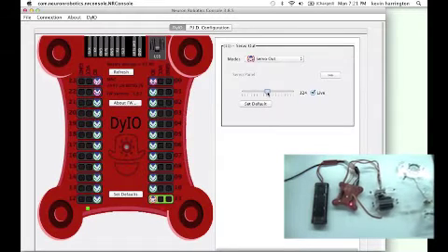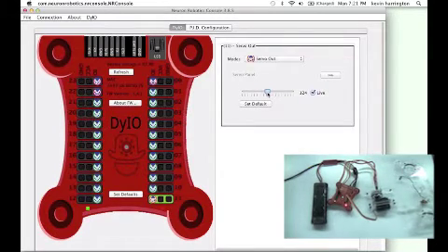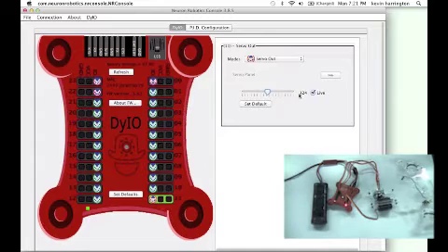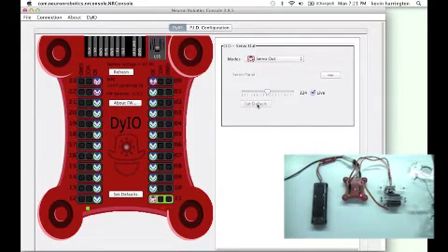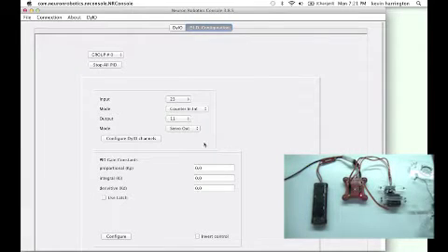What we'll notice here is that this particular servo stops on value 124. To let the PID controller know that that is where stop is, we set it as the default value. Now we come back to the PID controller and continue configuring.